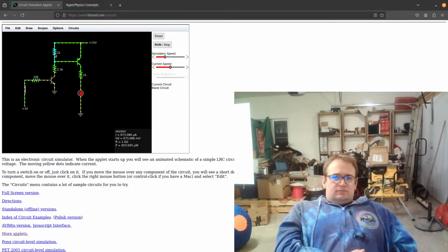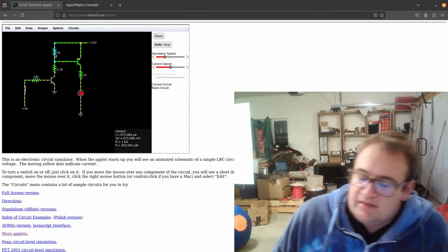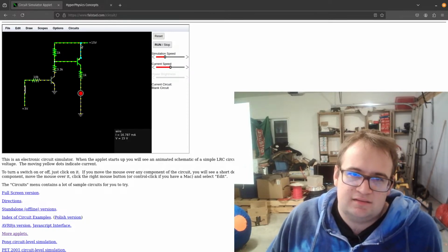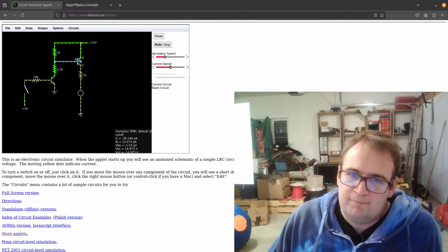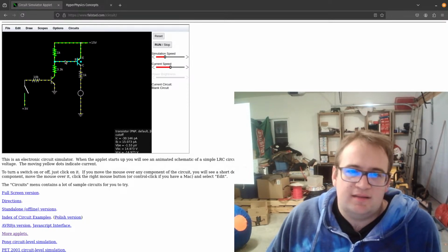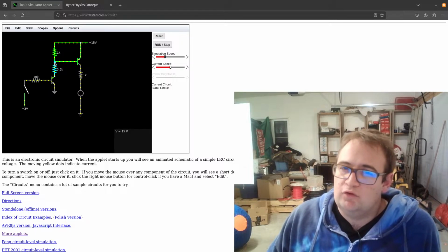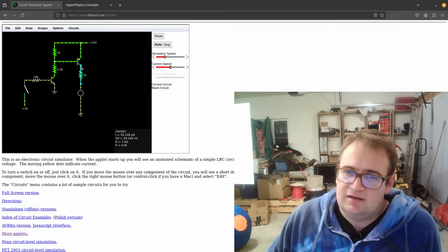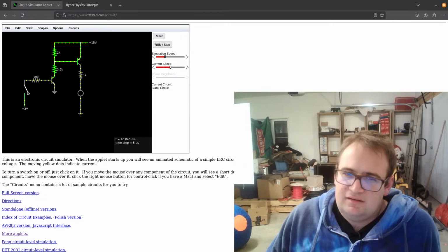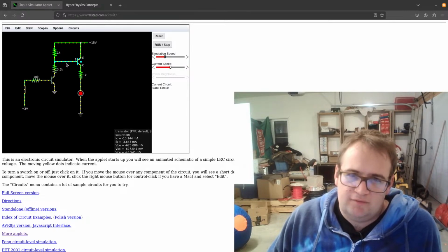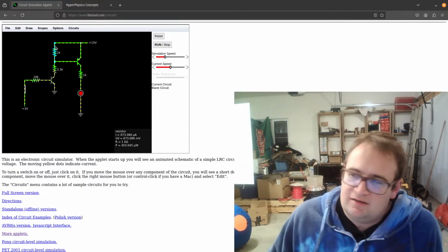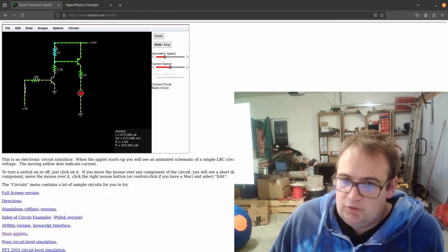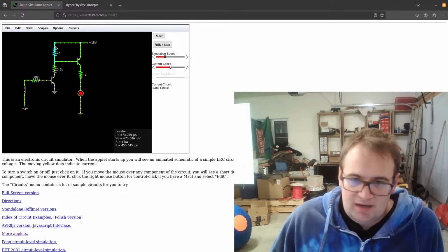So I think what I was misunderstanding, and I've done this before, is that since this is being held at 15 volts, this only has a one diode drop between them. And that means that this would be held at about 14.4 volts. And then this collector here would be tied almost directly to the emitter, because the current flows from there to there. So then it would be close to 15 volts as well, or 14.4. Let's see. Yeah, that says 14.4 volts, which makes sense then. And then that is why this only draws under a milliamp, because it's actually not dropping that much voltage. Like you see, it's only dropping 673 millivolts.